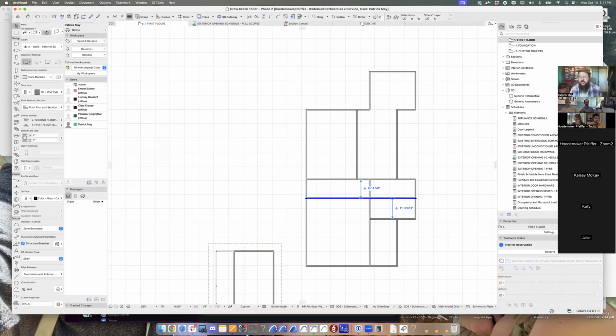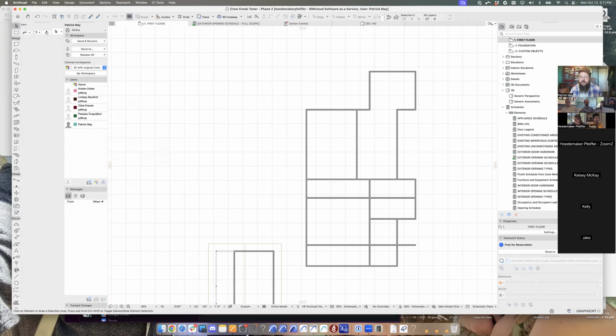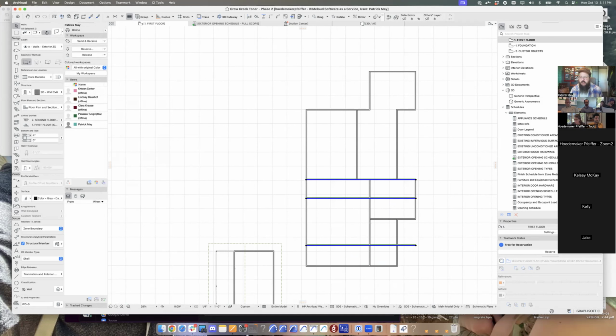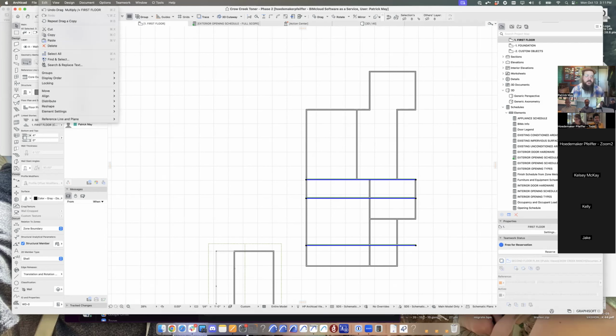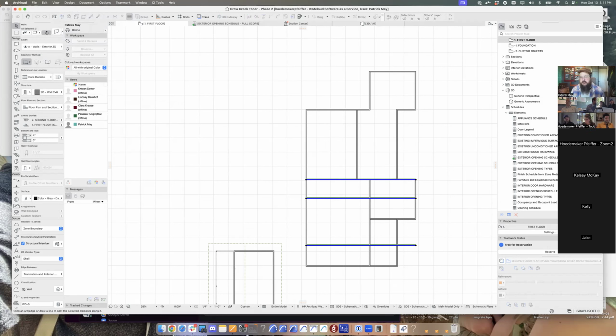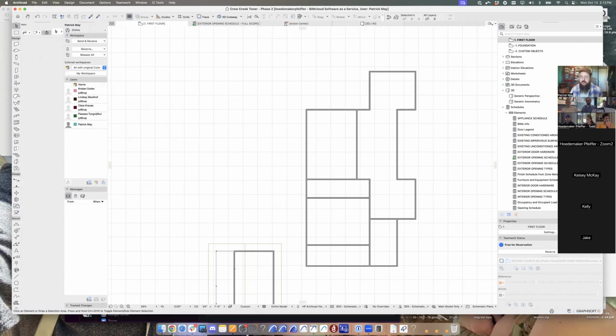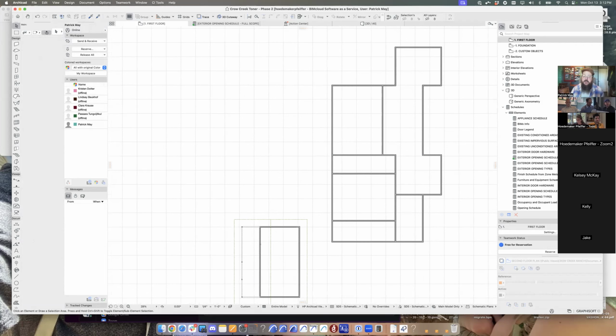Now let's just, as an example, say that I've got multiple walls and I want to break all of these walls from this point, but I want to keep them for some reason. That's where the split command comes in, this little hatchet icon, or edit, reshape, and split. If I split based on a vector, so hit split and break from here, it keeps those walls. So then I can offset those walls up a distance, or maybe keep one of them and delete the others, or whatever I need there. So command click and split command are both great for that.